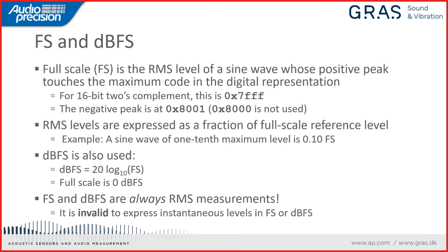So the issue with this, if there is an issue, is that not only does that mean that 1 FS or 0 dBFS is scaled to the full scale amplitude of a sine wave. That means that with the right signal, a square wave, for example, you can in fact have values that exceed 1 FS or 0 dBFS.